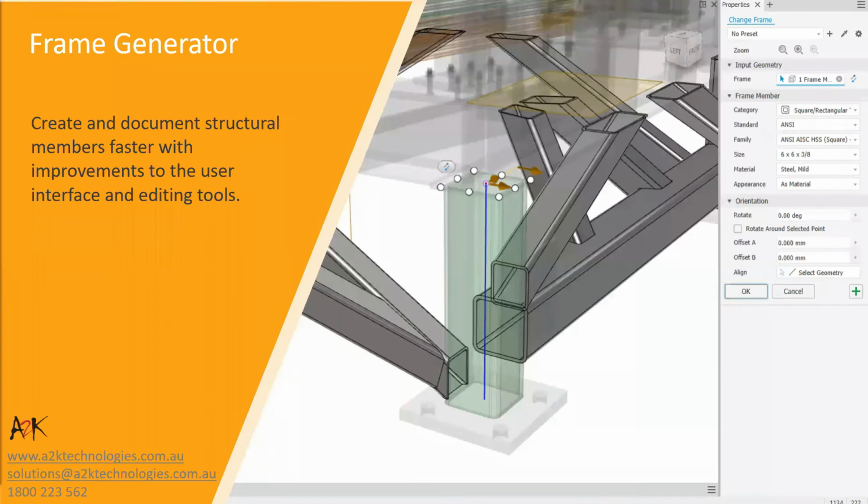Okay, frame gen. Now this is a big one. There's a lot of interest in the frame generator. So it's had several new enhancements in 2021. Improvements have been made to the file naming dialog, enabling you to have more detailed control of your naming schemes. Now, it's including the ability to set a file name of a component to be the same as the display name in the browser.